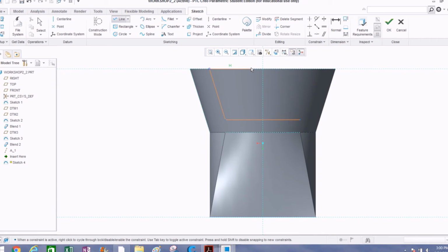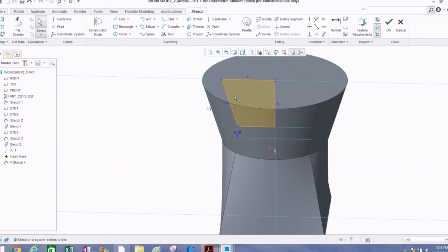Now this is a revolve cut, so we're only going to sketch 1/2 of the profile we need to cut this out. So basically we're going to sketch the left half. We're going to come to that center line right there, click once, and drag down to the bottom. You'll see it says midpoint, that's where we want to come to the line. And off to the right, center click once, center click twice. Now we need only this portion. We did reference this whole line, so we got this extra piece here. To remove that, come to delete segment, and delete that part. There we go. And if you center click once, you can see now we have our closed section, all closed in, looks good. And click OK.